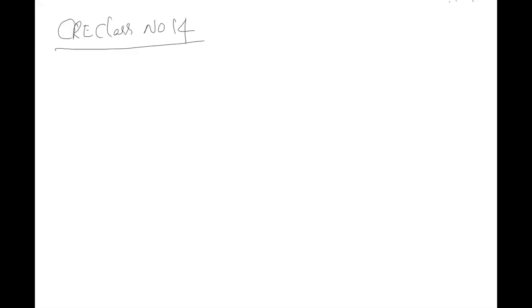Once you have kinetics, you can select a CSTR, you can select a PFR, or you can modify a PFR according to your requirement. Let's say I have a reaction A plus B gives C. A is positive order, B is negative order. Then you send A as the bulk fluid and B as a step input, or let's say multi-point injection. Clear? That is the concept, that kind of overall picture.